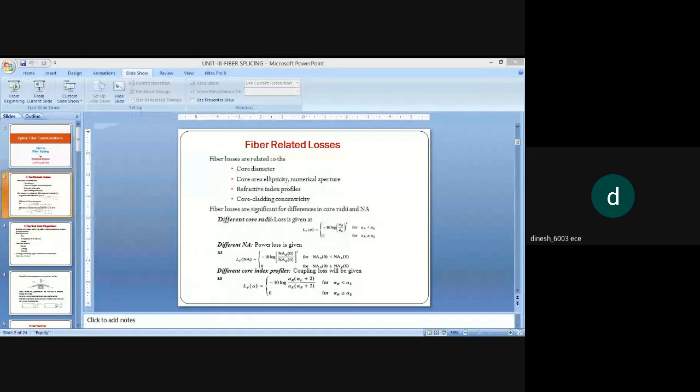Controlled fracture techniques that are used to cleave the fiber are shown in this diagram. You can see we have an optical fiber that we need to cleave at this point. We have a curved form, and there is tension. We hit it with a scoring blade such that the fiber is cleaved away. A highly smooth and perpendicular end can be produced through this method.